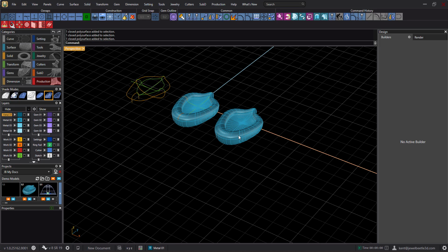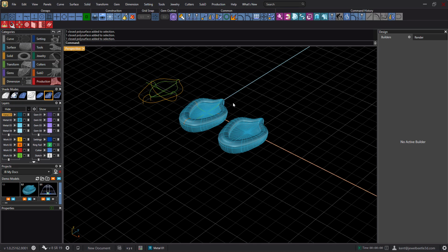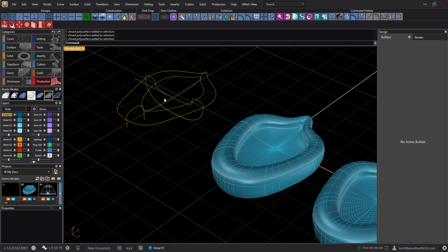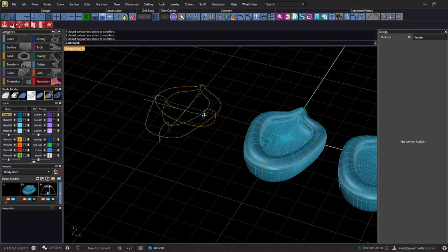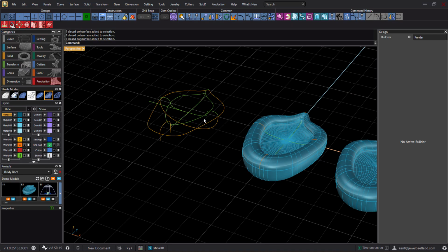I didn't know it was going to be a naked edge and so on. Kind of glad it was, because just typing chain, if that's the only thing that you really got out of this video, that's okay. I find that that's one thing that a lot of people don't realize you can do. You can use it in Loft as well.